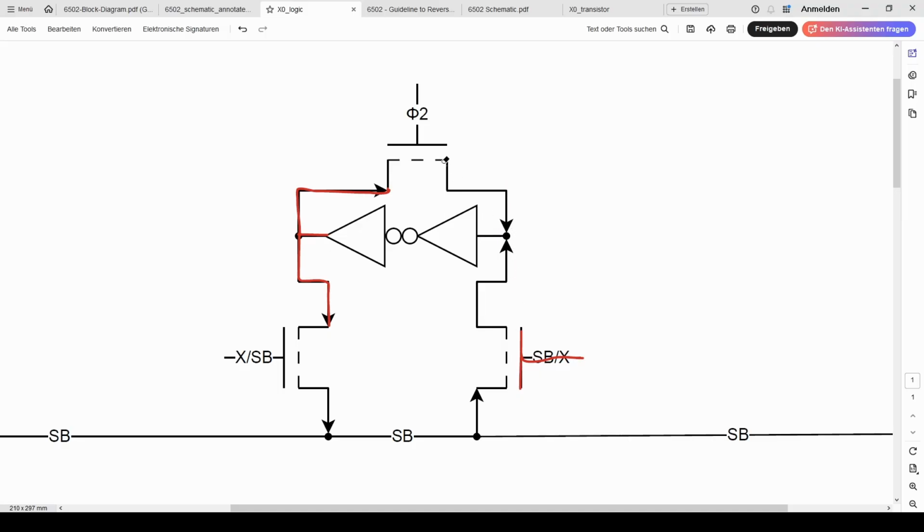and because there's nothing coming from here, because this is blocked, that then goes into here, which inverted to a 1, which inverted back to a 0, and that then turns this into 0. And we'll see in the transistor version how this then actually drains any residual currents here. But on this level, it's sufficient to know that it then just gets set to 0, right? And then of course, once we later on the next half cycle close this and re-enable this, it's just going to constantly feed 0 back in on itself.